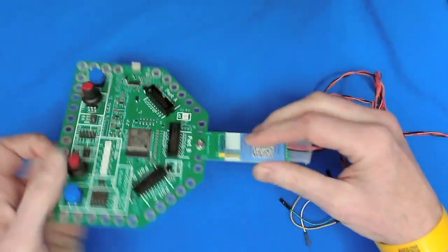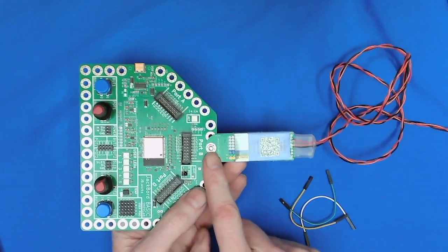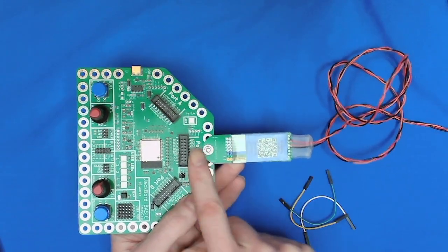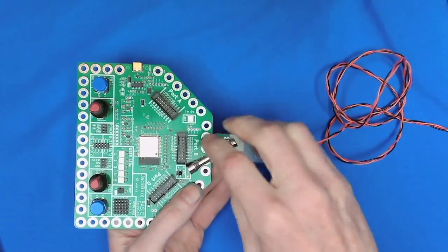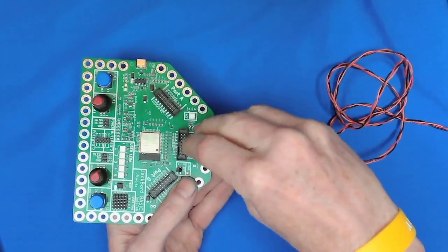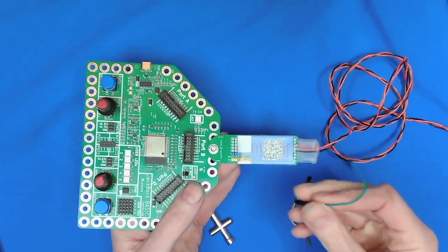So to connect the turbidity sensor to the JackBord Basic, first thing you do is just take the M4 nut and bolt it above port B like this, and then you just use the spanner to tighten it. Then in terms of connecting the pins, the first one we want is the ground.